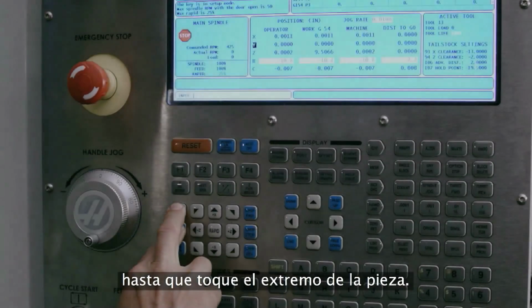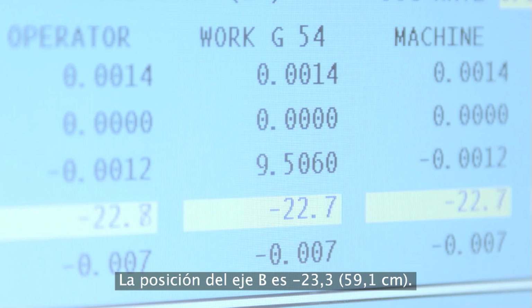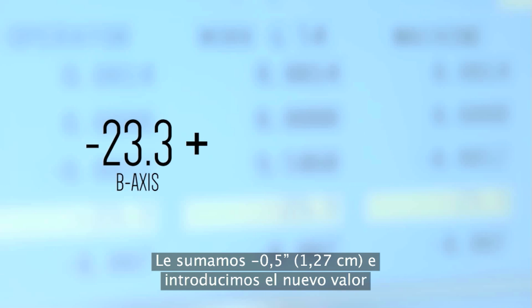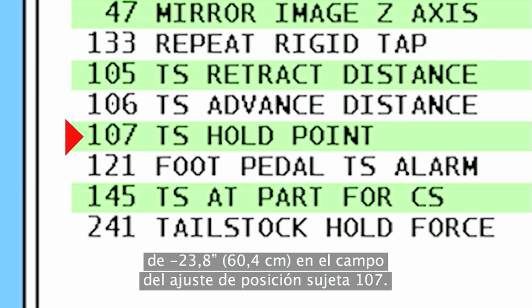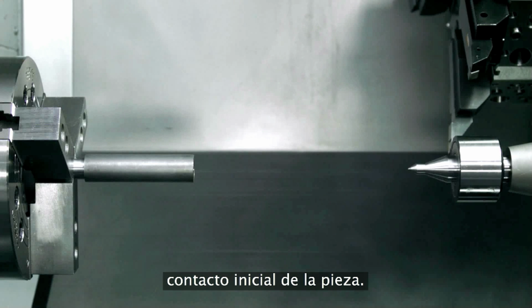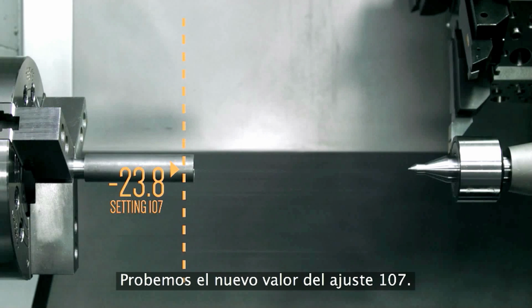To find a new setting 107 position, we jog B-axis forward until it touches the end of the part. The B-axis position is negative 23.3. We add negative 0.5 inches to the negative 23.3 value, and we enter this new value of negative 23.8 into the setting 107 hold point field. This way, the tailstock tries to clamp at a point beyond where it actually touches the part, allowing for minor variations in part length.